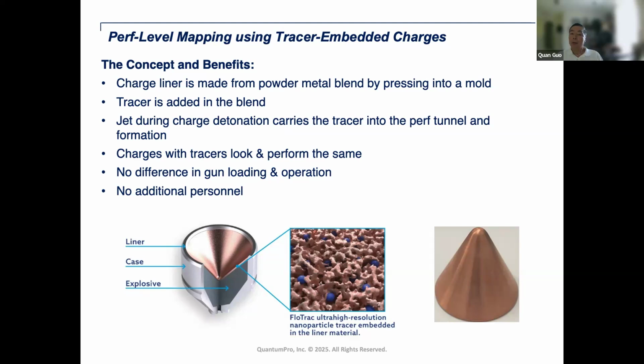And the charges with the tracers look and perform exactly the same as the charges without a tracer. There is no difference in gun loading or wireline or TCP operations. No additional procedures are created from this, and no additional personnel is required. So we don't have a person or engineer on the well to deploy the tracer. So this does have many advantages. The concept is quite straightforward.